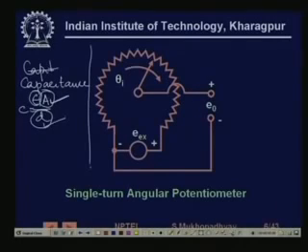Now you have to note that if there is a change in area, then the change in capacitance is actually linear with respect to the change in area, while it is not linear with respect to the change in D. So this must be remembered, because as we explained, we generally look forward to a linear characteristic in sensors, basically because of ease of use.